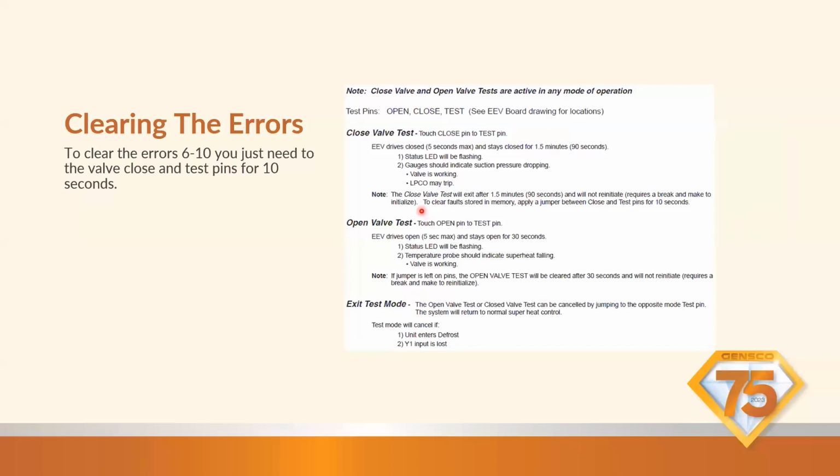When you do that, you're going to clear the faults in the stored memory. Apply a jumper between test and close for 10 seconds. So you're going to hold it on there for 10 seconds. After 10 seconds, you can remove your jumper and the errors should clear themselves.